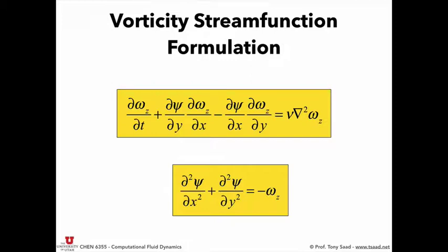So omega z is equal to dv by dx minus du by dy. There's no v. So omega z is really minus du by dy. OK, so what is the direction of vorticity here? So what is du by dy? Over here, du by dy is 0. There's no change in u in the y direction. What about here? Is there a change in u in the y direction? Here, all the way, it decreases as you go up. So there is vorticity over here.